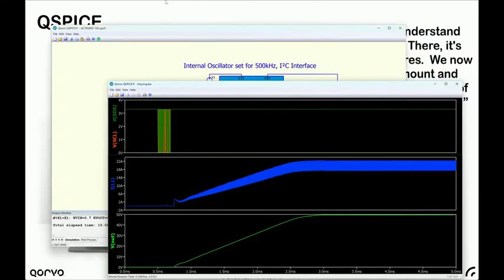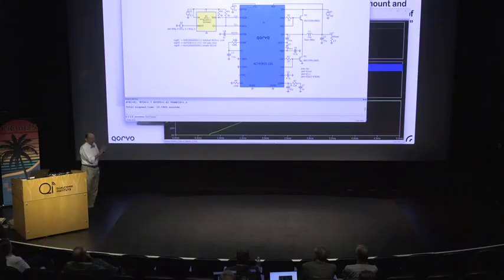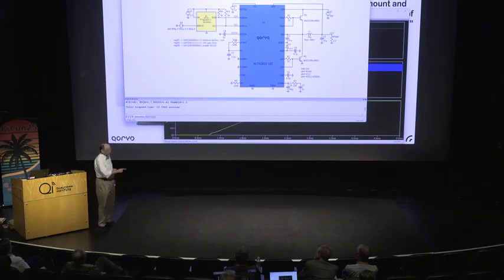What I'm saying is, the nice thing about a good simulator that can handle more complicated circuits is you don't have to simplify the thing. You don't have to say, oh, I sent these I2C registers over to the thing. Well, this one actually won't even turn on until you tell it to with a command. Yes, you should always simulate as small a circuit as possible, but you have to be careful of simplifying assumptions, and you would like the simulator to make it so you don't have to make as many simplifying assumptions. You won't see a power IC that's controlled by I2C, CAN or SPI where you don't just somewhere say, oh, these are these values, and stick it into the back of the part as a global parameter. You actually just simulate the literal circuit. So it makes the process less error prone.